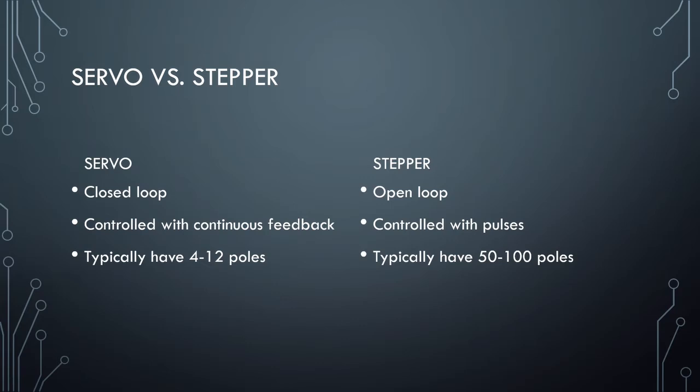Depending on what sort of speed, what sort of torque you need, if you need a quiet application, if there's a lot of vibration going on, there's a lot of different variables that come into play when you're selecting a motor. And depending on the environment and what it's being used for, in some applications a servo motor might be better.